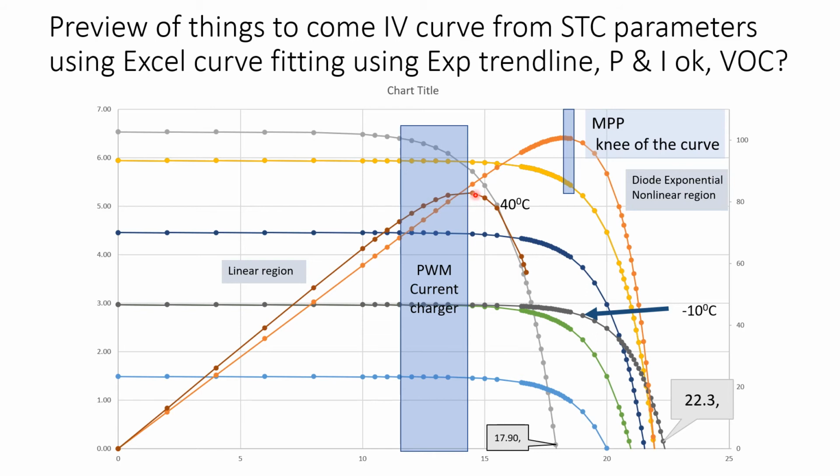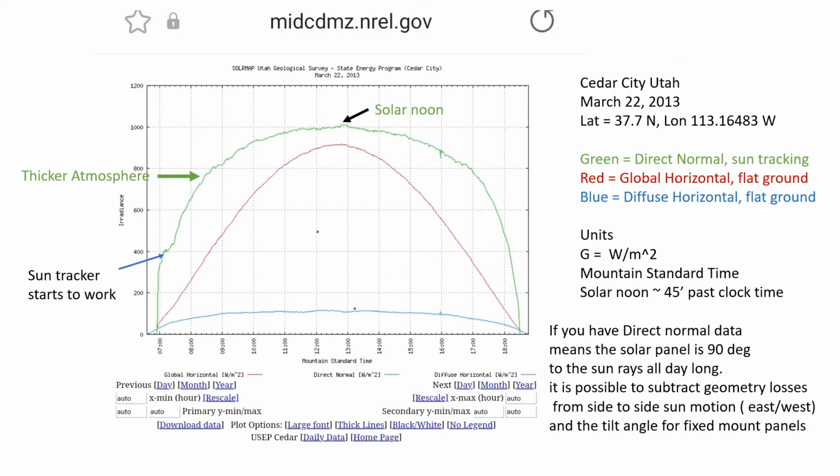All right. So I just threw a whole lot of information at you, and I do realize this is an eye chart, but it tells you a lot of information. And I derived these charts from just 3 data points: short circuit current, open circuit voltage, and the max power point for the panel at STC. All right, let's go on to the next graph.